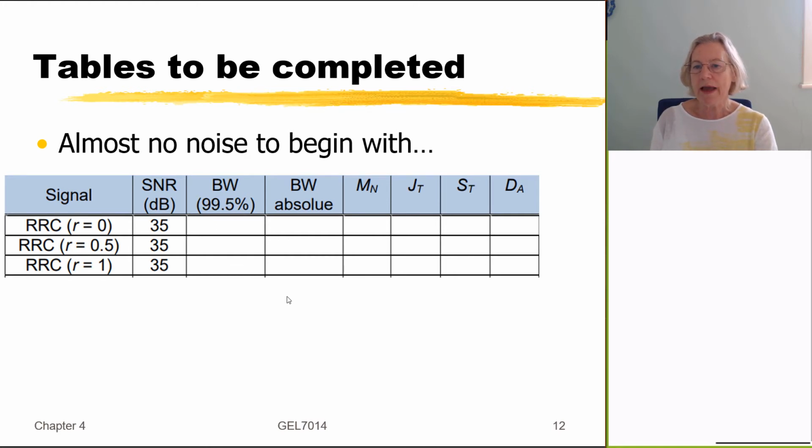So we'll be looking at bandwidth, which we'll concentrate on during the high signal to noise ratio, and then we'll also be taking some values which are measured directly from the eye opening, and I'll be talking a little bit more about what these values are. When you observe the eye opening, you'll be able to measure them with it. And of course, when we change the signal to noise ratio, the bandwidth really shouldn't change, but these values will change because they'll be influenced by the noise level.